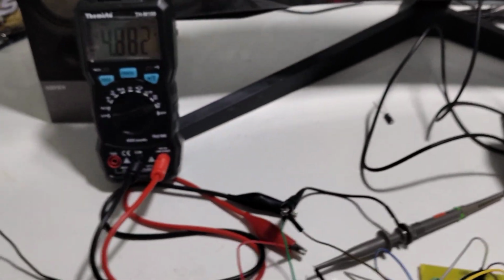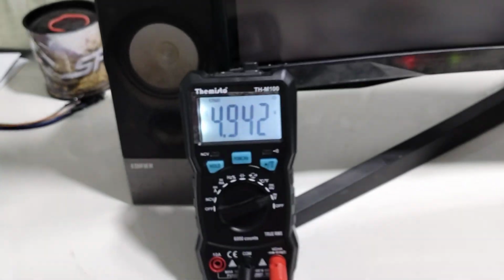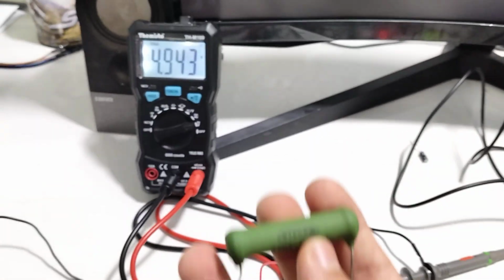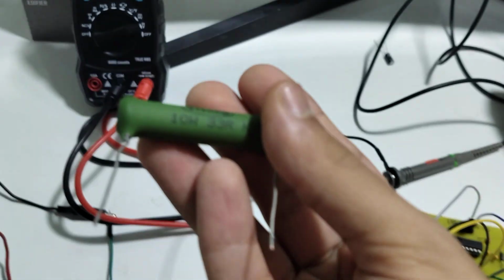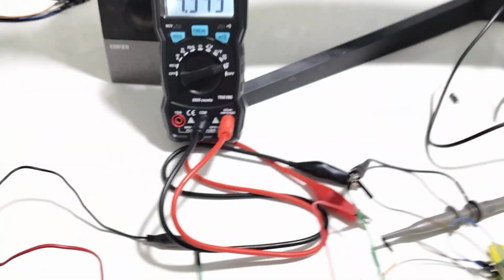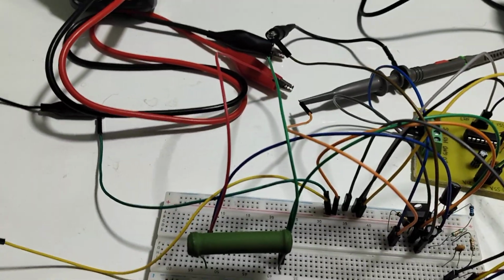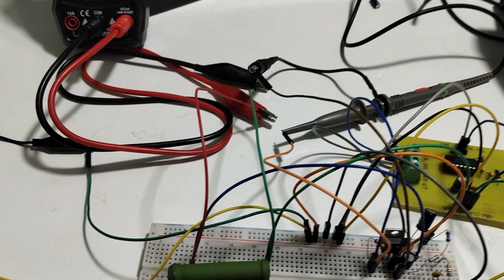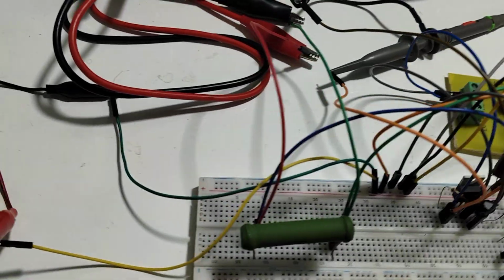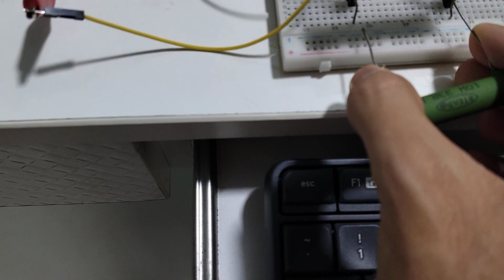And another way to demonstrate this is, let's say you add a heavier load, right? Currently, look, you can see now it's at 4.9. The steady state error is being rectified. So now let's say I have another resistor in my hand, 33 ohm, sorry. So currently it's 100 ohm, right? If I make this in parallel with this, basically the current draw will increase, right? And if this output voltage is still maintained, then you can declare that your closed loop control works fine. So that's what I'm going to be doing now. We have this 33 ohm, right? So now I'll just put it in parallel with this.